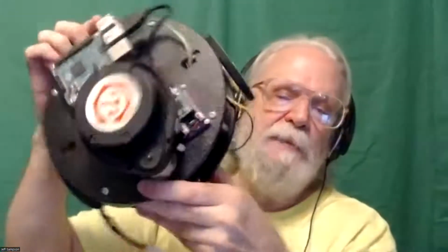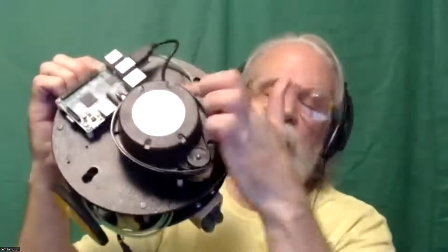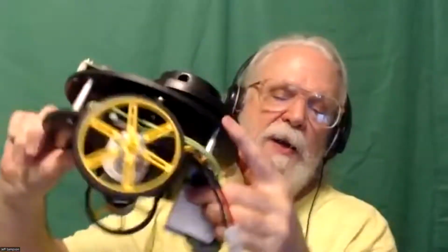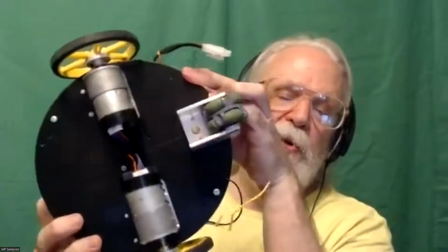So I could put that kind of stuff directly onto this because this thing isn't very big. This is what, 8 inches in diameter, and it's got a full ROS computer on it. It's got a LiDAR on it. It's got DC gear motors on the bottom with encoders, and then it's got this cute caster wheel. It's one of those Omni wheel things, so you don't have a regular caster wheel swinging around like this and causing problems. It takes up no more room than what you see right there.